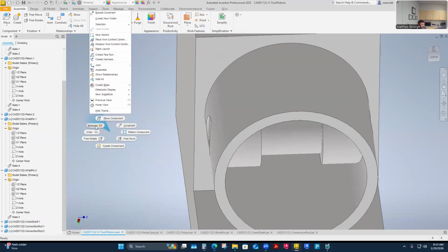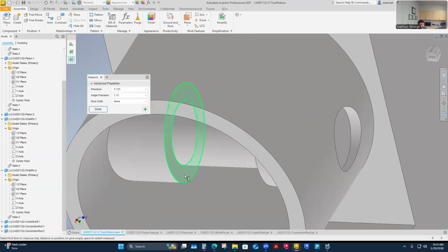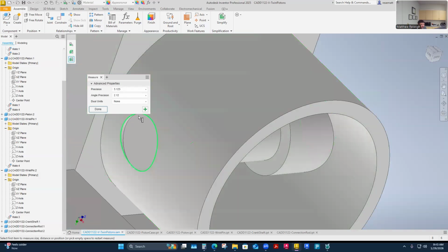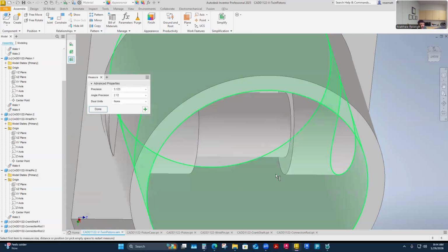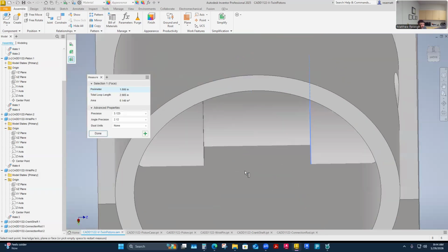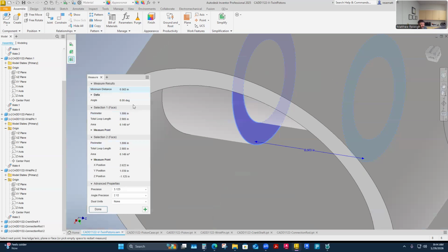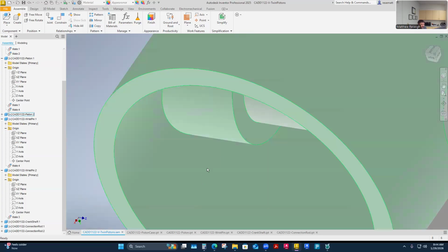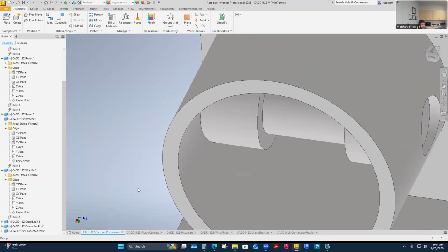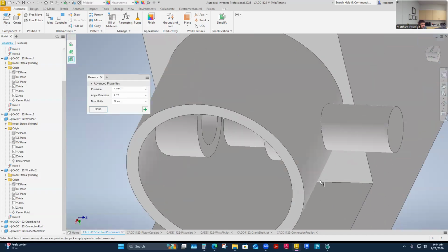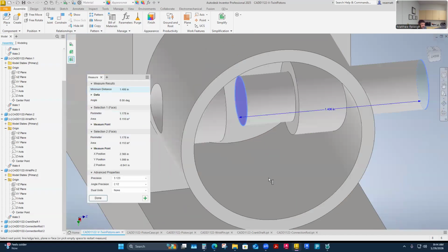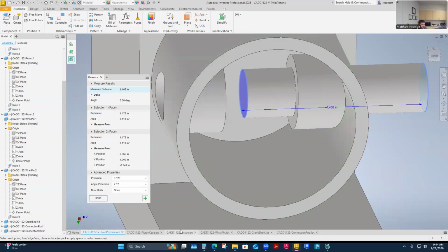These two faces are a little bit easier to work with than trying to pick a point on this contour cut face. Maybe there are some points here that I could pick, but I'm wondering, what is this between this and this? Well, this is 0.563, which is really 0.5625, but 563 would be close enough in some ways. Then I would have to know how long my pin is. How long is this pin? Oh, it's 1.406, kind of a weird odd number.